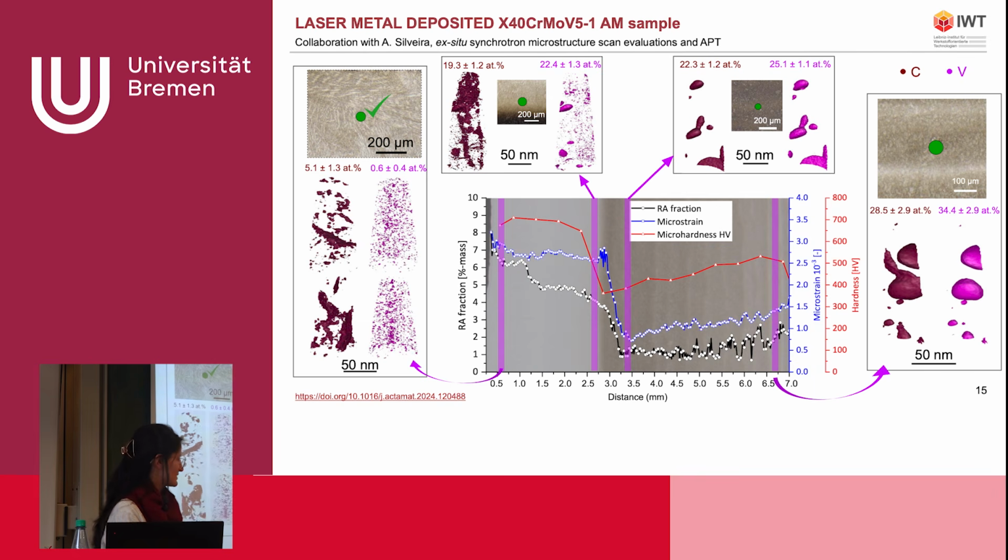In the case of carbides, this is actually the case because the carbides have a very specific field of evaporation. When the voltage is applied to the whole sample, the carbide is just on one part of the sample, so we have a difference in the speed at which the sample is evaporated in the matrix and in the carbide. So there are of course some artifacts like that, but we can correct for them and still rely on the results we have from atom probe tomography.